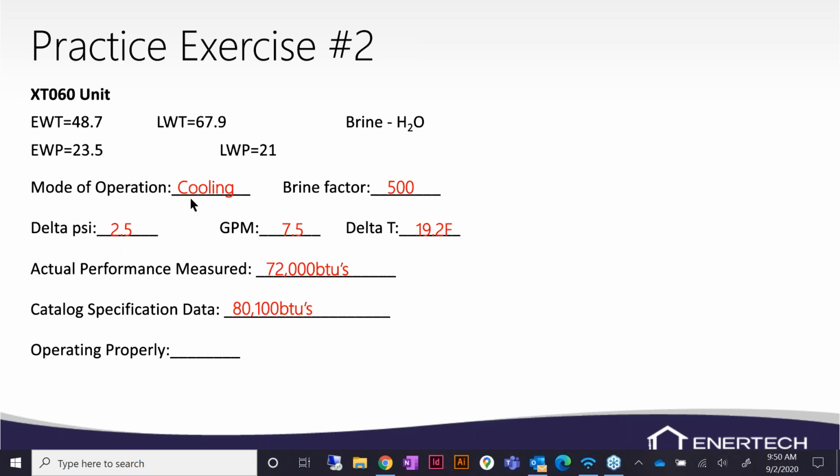Well, you asked, are we going to do water to water? I don't necessarily know what you mean by that, because the heat of extraction and heat of rejection don't change because of the type of unit. It's the same calculation. It doesn't matter if it's a WT, WS, a variable speed water to water, split unit, or packaged unit. It's the same exact calculation. We're always checking source water.